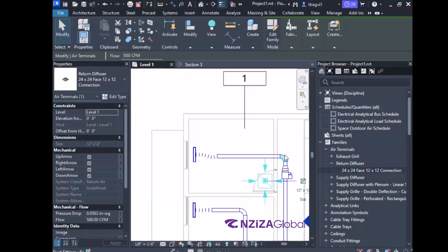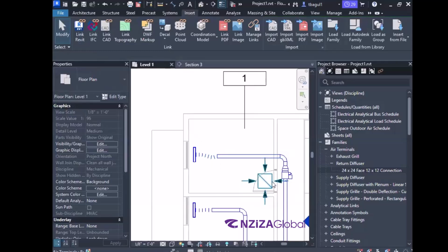So the one more point in the room was for the team online: how about the proper flow of the air to make sure that the air is properly utilized as an exit for the contaminants, right? It should not keep on revolving in the room itself. So for that, yes, as I mentioned, try to keep the diffuser first of all closer to the facade, with the exception that it is not directly falling on the head of the patient, right? And then try to make it as diagonal as possible so that the entire room is covered with the airflow. Does that make sense? Oh, perfect.